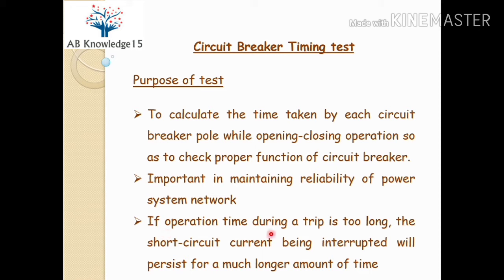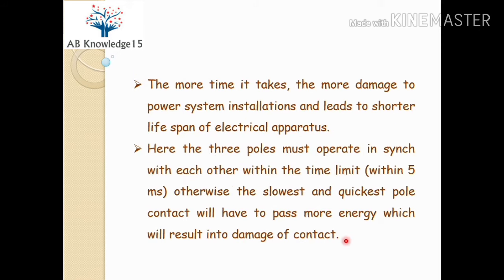If the operation time during a trip is too long, then the short circuit current being interrupted will persist for a much longer time in the circuit breaker. The more time it takes, the more damage it will create to the power system installation, which leads to a shorter lifespan of electrical apparatus.